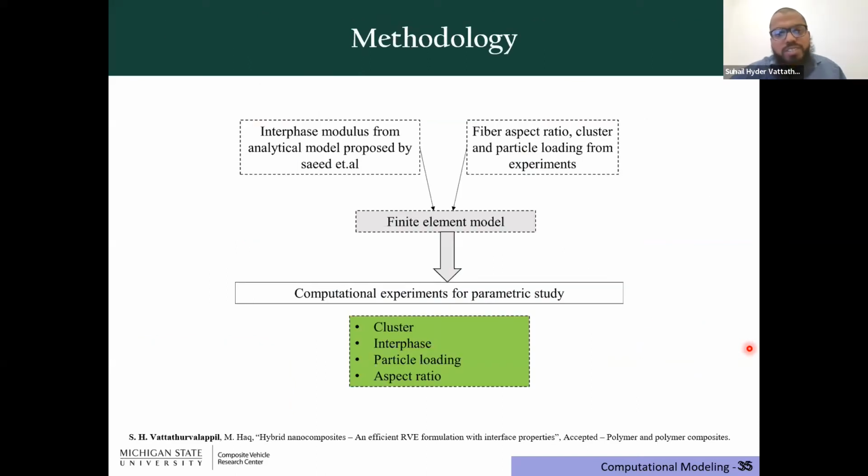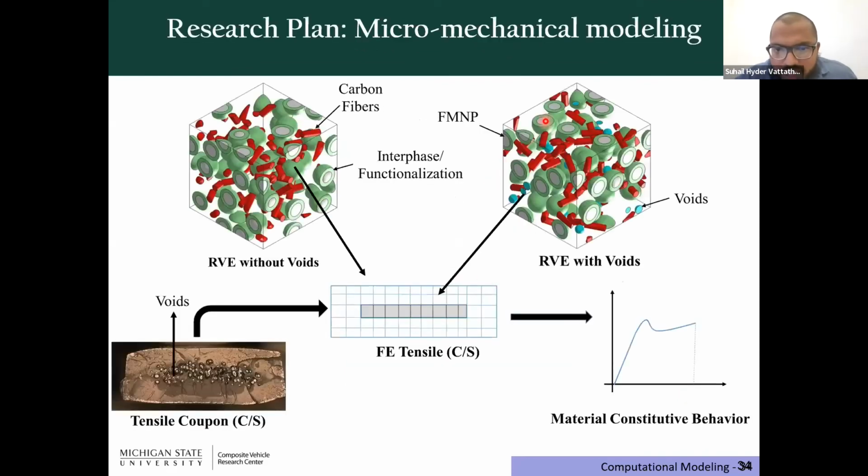And we also used an interface modulus. For instance, if you come over here, you can see that the ferromagnetic nanoparticle is this ash white in color, and the green outer surface is actually the interface. In nanomechanics, when you have polymers and nanoparticles, there is a region just outside the nanoparticles, and that region will have neither the properties of the nanoparticles nor the properties of the polymer.